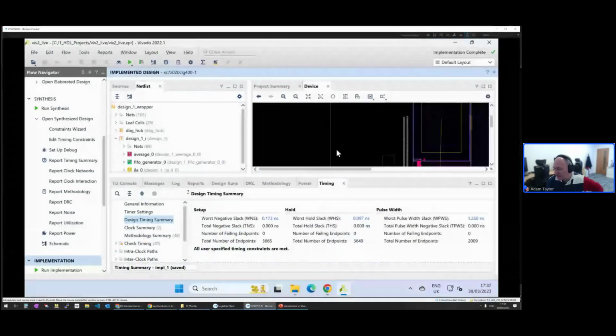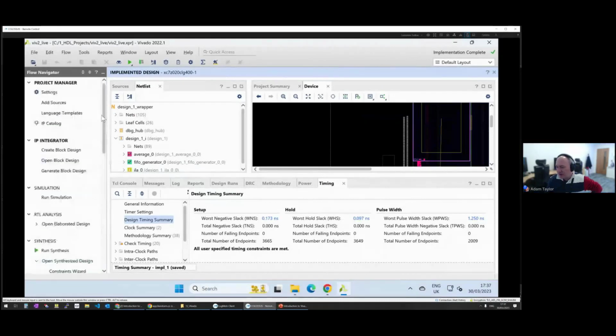So for large scale debugging, I would say, and actually it's one of the things that I'm going to be blogging about in the next few weeks, Vivado simulator has the ability to do functional coverage using SystemVerilog assertions. So when possible, I would try to use standard simple things of simulation, functional coverage via assertion-based verification,